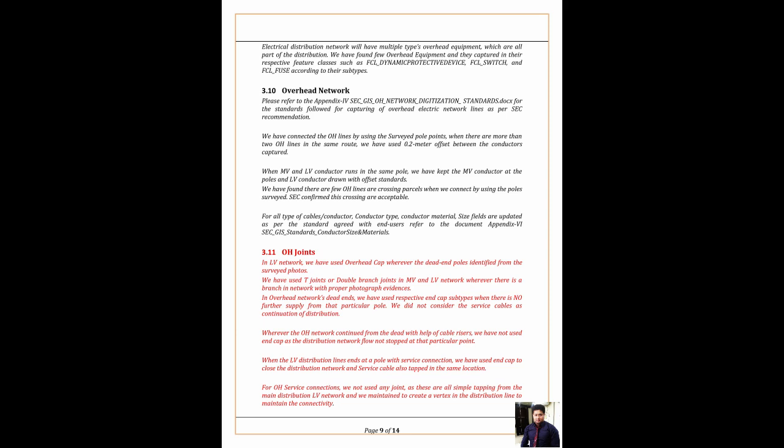We did not consider the service cables as continuation of distribution. Wherever the OH network continued from the dead end with the help of cable risers, we have not used an end cap, as the distribution network flow has not stopped at that particular point.